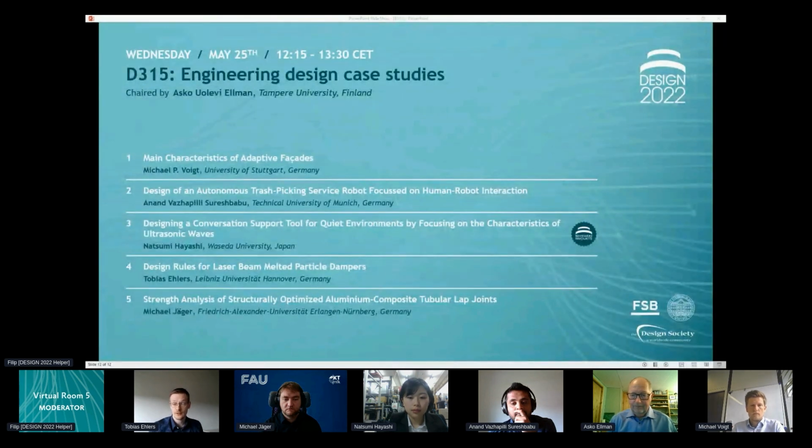To the first question, I don't want to change the shape of the cavities, because when you have a cavity with a high dimension in the height and in the width, we also have to manufacture the beams, and in additive manufacturing we have the 45-degree angle, and that is easier when I have a cubic volume. So I don't want to change this. But in the literature, there are also some investigations about a cylindrical cavity. But that is not really my research.